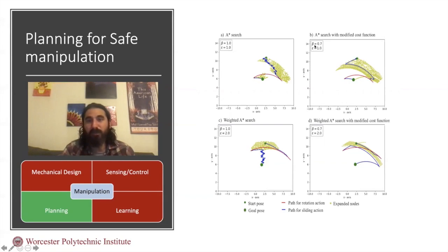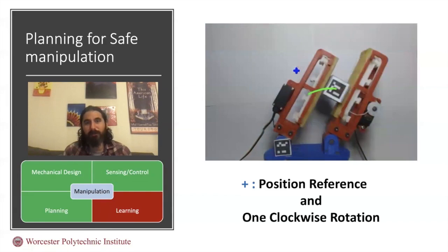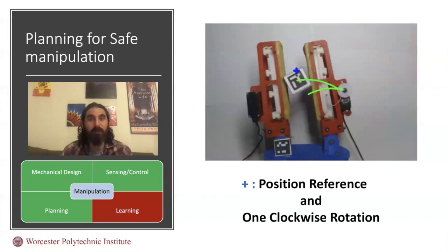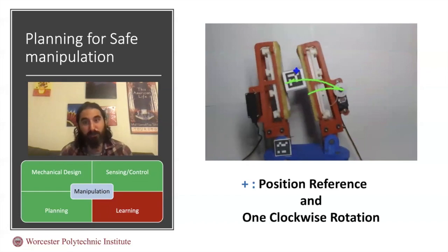So we had two control parameters on our trajectory here. One was reducing the amount of switching actions, and the other one was making our search more greedy. By combining these two, we were able to have both efficient paths and the least amount of switching possible. We combined this planner with a visual servoing algorithm so that we can achieve robustness to modeling uncertainties of the hand-object system.